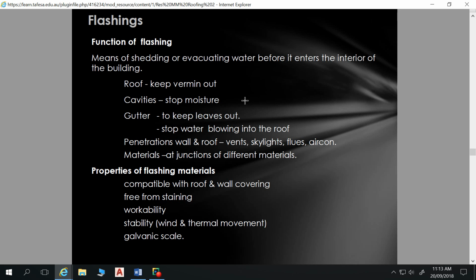However, it's not too much of a consideration now, because a lot of your flashings are made specifically. Well, you've got flashings made of exactly the same material as the rest of your roof, or you've got these flashing products that are bitumenized with a piece of aluminium inside there, and you don't have the conductivity between that aluminium and the steel of your roof as well.